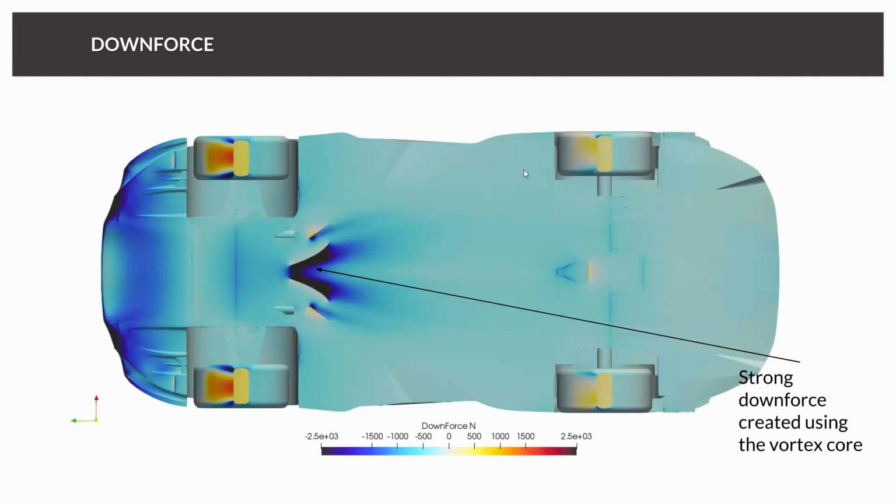And Kazu wants to know, when the car is turning, will the underbody vortex be disturbed? How does SimScale model this? What do you mean with turning? So the car is turning into an apex or into a corner, or what do you mean with turning? Because if you want to simulate the aerodynamics around a turning car, it's also possible with SimScale, but it becomes a little bit more complex because during turning, actually, the velocity field is changing more. So you would need to really model a corner and add a global MRF zone to the whole simulation.